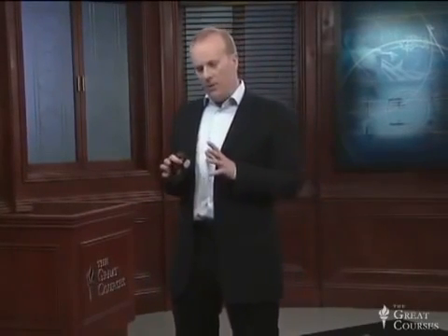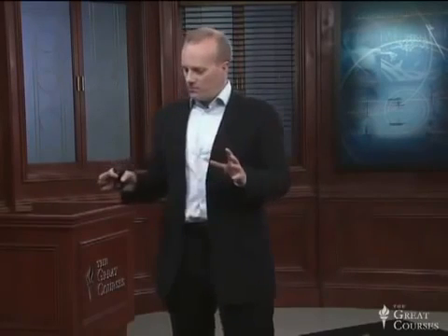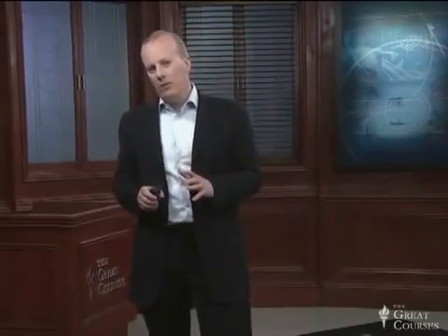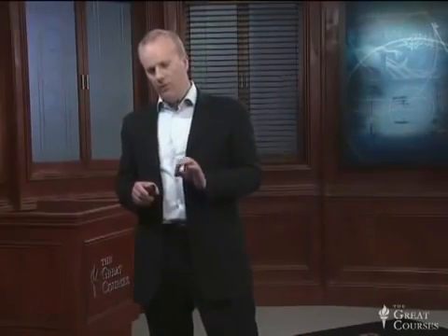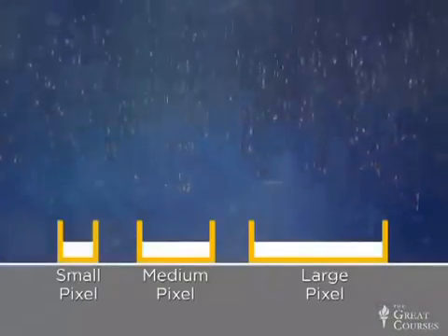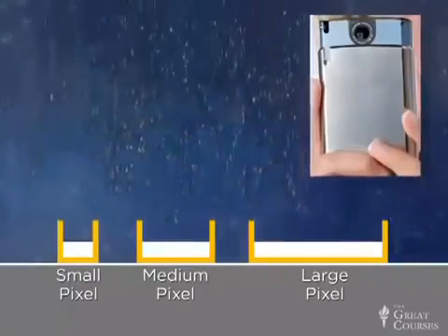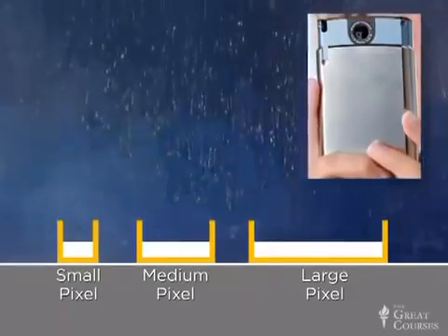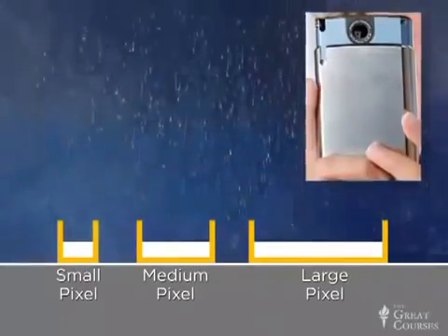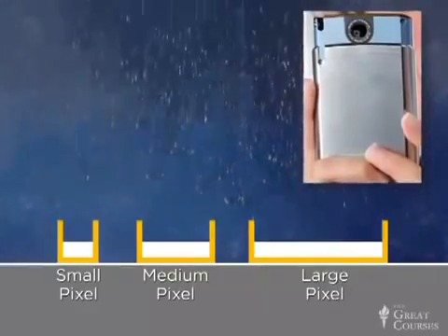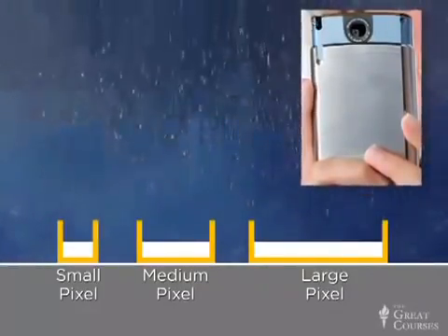So it means that there's this constant pressure to shrink the dimensions of the components of these integrated circuits and the integrated circuits themselves to become smaller and smaller, more and more compact. That is great news for fitting more megapixels into a given area. But there are some compromises that we'll talk about in a second when you shrink pixels down further and further. The bottom line one is that you end up having fewer and fewer photons impinge on each pixel. So if you're taking a picture with your cell phone camera and haven't always been satisfied, maybe especially in low light, that's a consequence of this shrink down in the number of photons that impinge on each pixel as a result of shrinking the pixel.